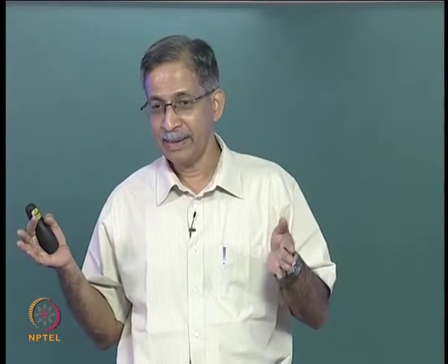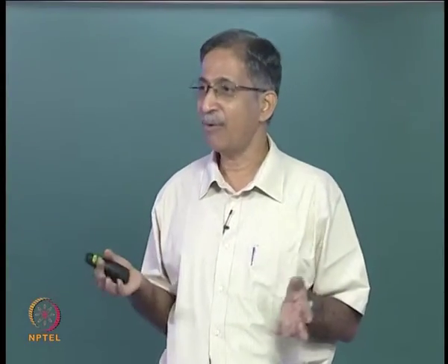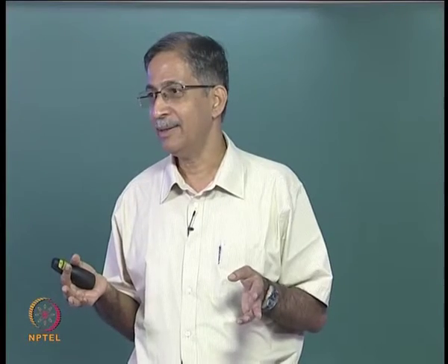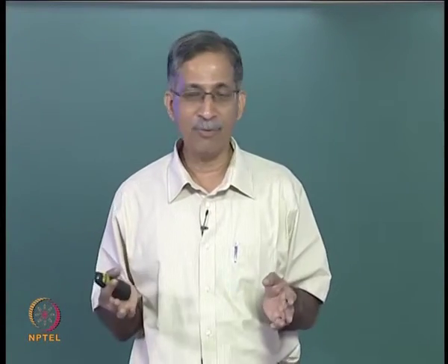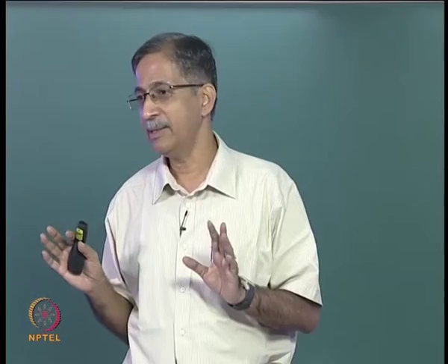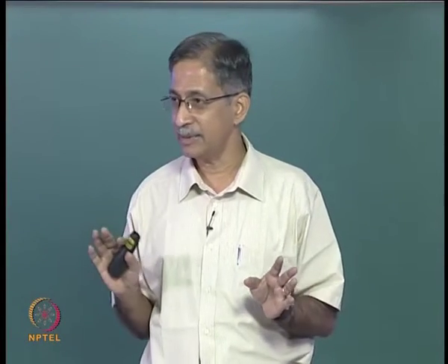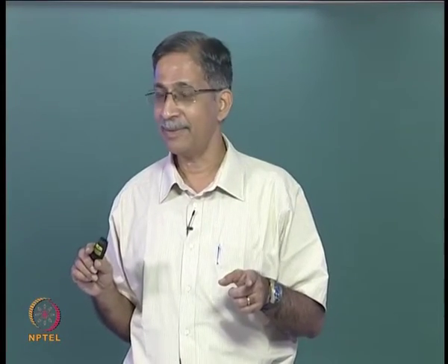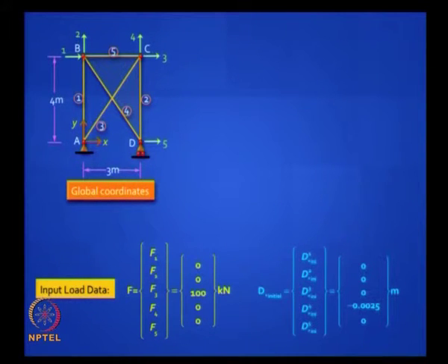All the other members will retain the lengths that they have been manufactured with, and the joints will just move. So this is something that you know, that in just rigid statically determinate structures, if you have a lack of fit or a temperature change, it does not introduce any internal forces, it does not introduce any support reactions, it only affects the geometry. You will get joint displacements. Is it clear? That's how it works in a statically determinate structure.